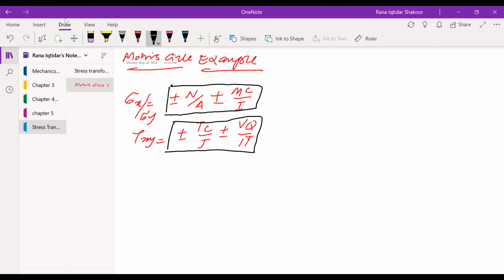And these two components contribute towards the normal stresses. So whenever you have different types of loading condition, you have to decide whether this particular condition will generate normal stress or shear stress, and then accordingly, looking at the directions, you can move plus minus of all these. Then you end up with some certain 2D state of stress or planar stress, because we are assuming that there is no stress in the z direction, so we are left with only sigma x, sigma y, and tau xy.